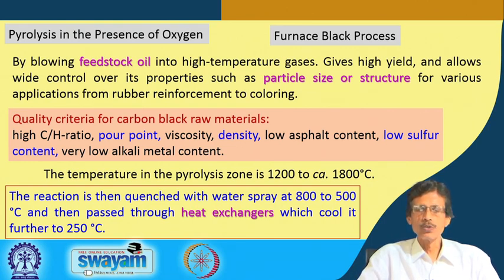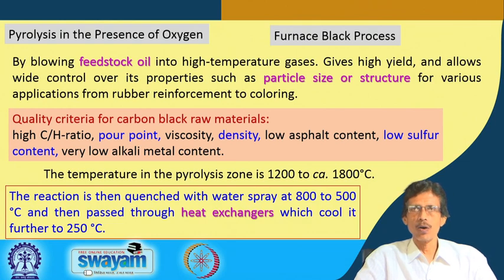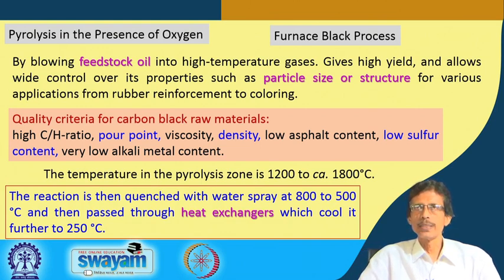The reaction is then quenched with water spray. So, the water spray is utilized, basically for washing also, at a temperature of say 500 to 800 degrees centigrade. So, the water temperature can also be very high, and then ultimately further cooling, that means it is a stepwise cooling. Suddenly we are not going for a chilled condition. That means, if you have a temperature of 1200 to 1800 degrees centigrade, then suddenly going to room temperature, we are not allowing that.